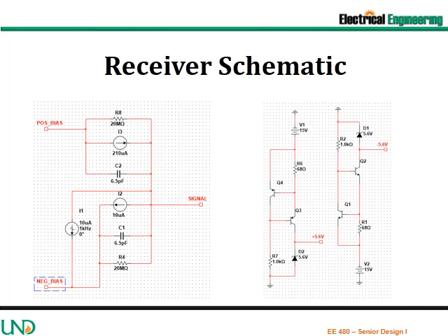The model of the photodiodes is shown on the left. This model was developed based off of the 5.6 volt bias from the datasheet. On the right is the low impedance bias. A constant current source and sink feed the Zener diodes to create a constant voltage. The current draw from the diodes through the bias is negligible compared to the current through the Zeners. The Zener diodes have a low dynamic impedance as well, resulting in a low impedance return past the ground.